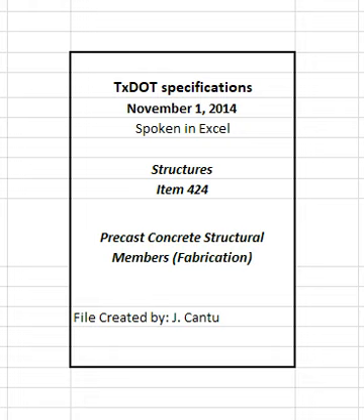The following curing requirements apply for non-stressed members. Cure concrete continuously, except as allowed during form removal, for 4 days, or until the compressive strength of the concrete has reached the design strength. Maintain concrete temperatures between 50 degrees Fahrenheit and 150 degrees Fahrenheit during the curing period. The maximum allowable concrete temperature may be increased to 170 degrees Fahrenheit if the contractor uses one of the concrete mix design options listed in Section 421.4.2.6, Mix design options, other than options 6, 7, and 8.